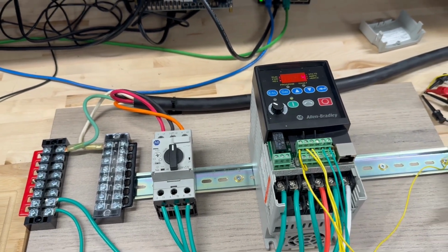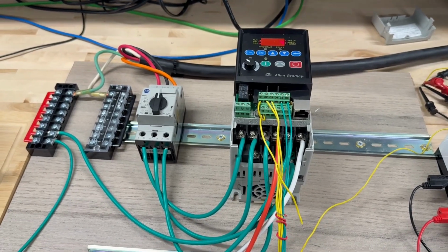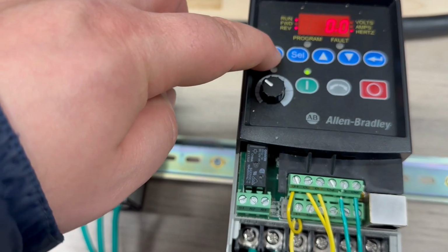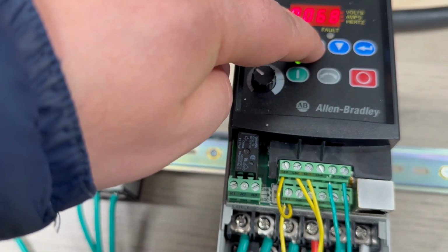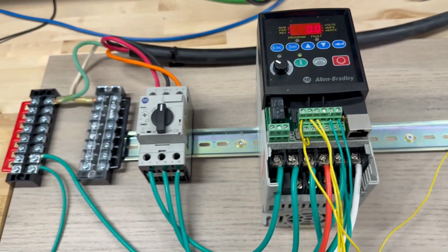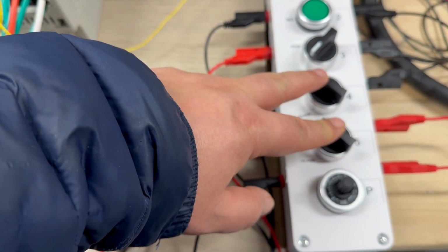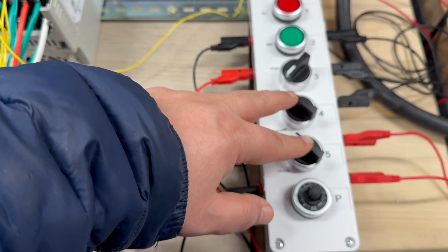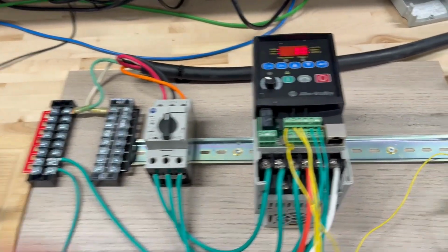The next are A70, 71, 72, 73. We are not adjusting them; I think they are already on the default. Let's check them again, starting from A70. A70 is 0 volt by default. That means if both these inputs are 0, meaning terminals 5 and 6 both give 0 volt, it should be frequency 0, which we adjust with A70.